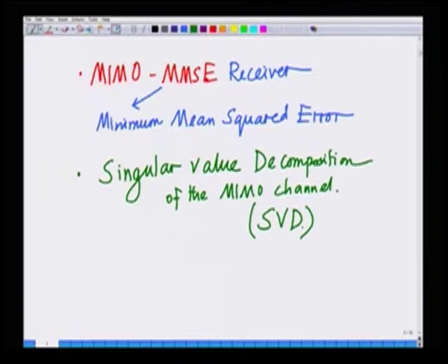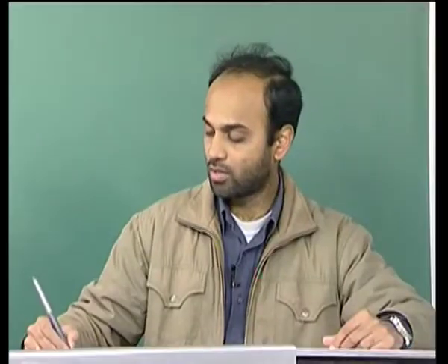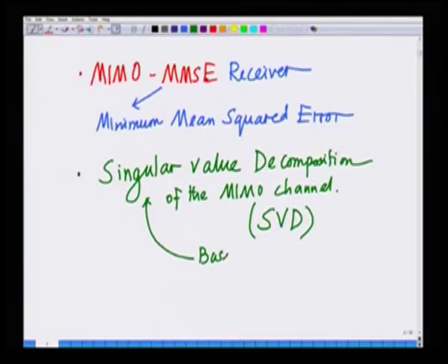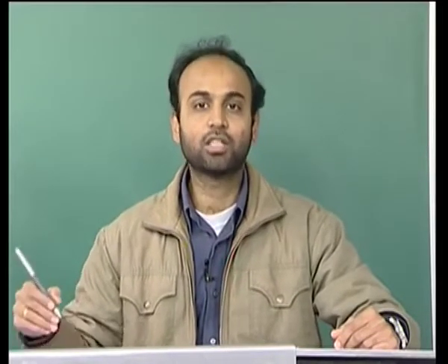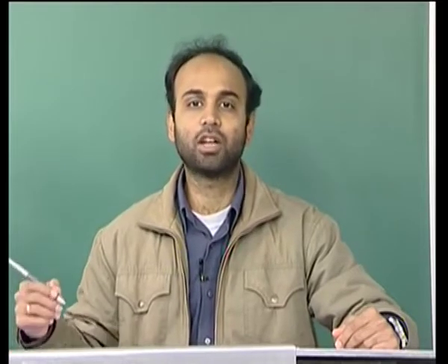We also said this is based on precoding at the transmitter and receive beamforming at the receiver. This is based on a precoding structure, which is essentially a transmit pre-processing that has to be done at the MIMO transmitter before transmission.